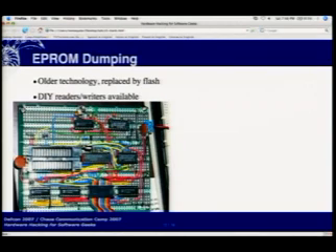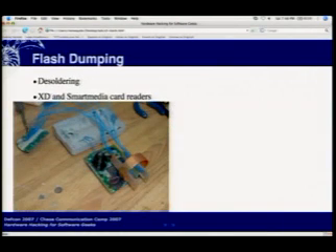Another thing where resources from the embedded engineering or forward engineering process come in handy is when you've got decompiled binary. So the first thing you look for are vectors that are defined in the chip spec, like the reset vectors and the interrupt table vectors, and figure out where the code starts and where it goes when it jumps from the code it's executing to an interrupt, and then back. The general first interrupt that's going to get serviced when the chip starts up is the reset interrupt vector. If you can find out where that is, that's the entry point for your code. You just tell IDA this is the entry point and it'll figure it out. Exactly, the G spot as it were.